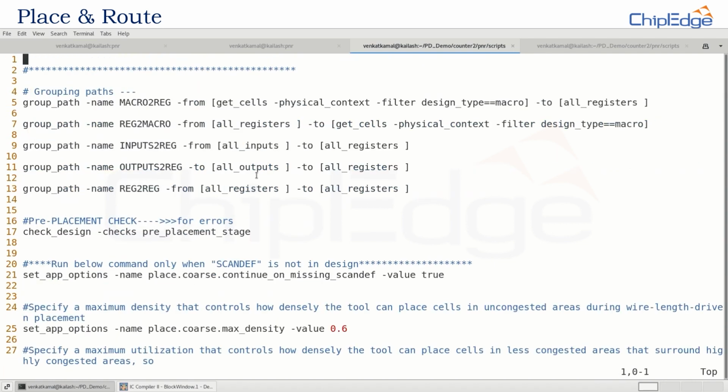This is the Tcl file that is made for executing the placement of cells, the placement of macros, and placing the blockages between macros. Blockages are nothing but a restriction between two macros or in the open channel space, for restricting the cells from being placed in between macros or in the crucial channel spacing or routing.